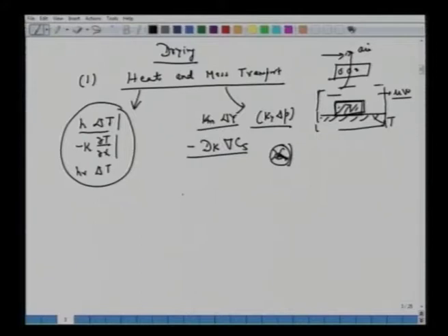All right. Of course both of them will have an independent effect, but in some cases you can see that heat can improve this Knudsen diffusivity. So it has a simultaneous effect also. We can have unsteady state problems, a function of time. If you start with a solid which is cold, at room temperature, and now you bring it to a very high temperature, it will take some while before the temperature of the solid becomes the same as the temperature of your heat plate. So it's a function of time. We can have an unsteady state problem, or we can have a steady state problem.